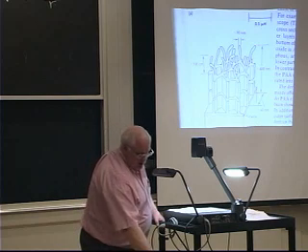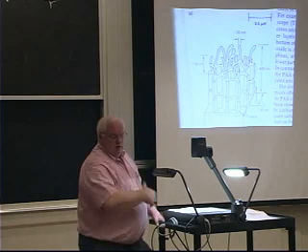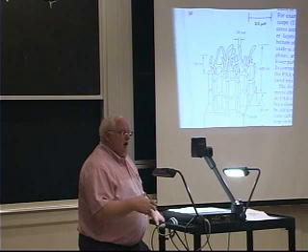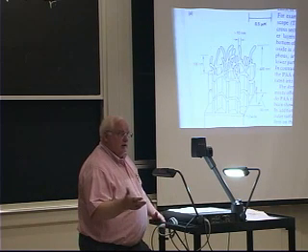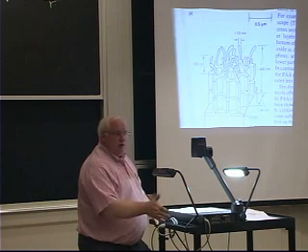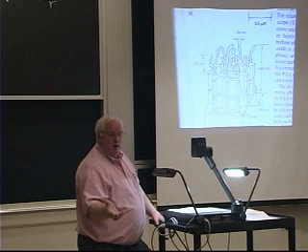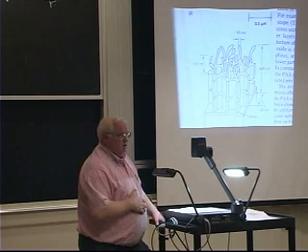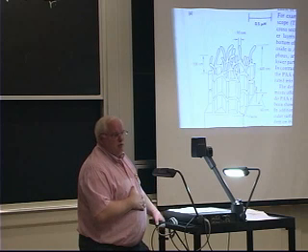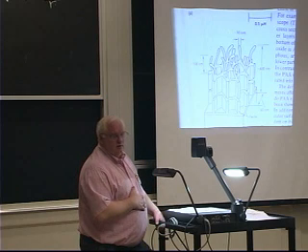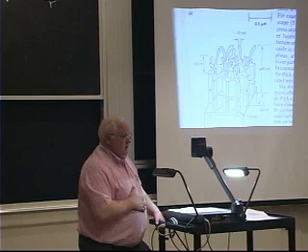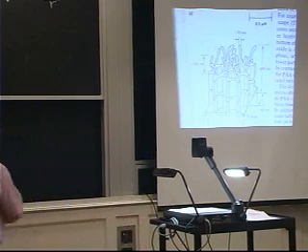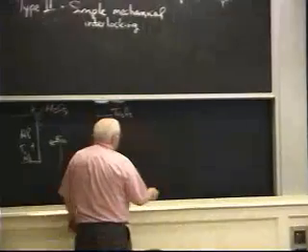My oldest son's Eagle Scout project was a bunch of railings, outdoor hand railings on a building. This is back in 1986 or 87. The building had been built in 85 and all the paint was coming off this galvanized steel two years later, just peeling off in great big sheets. They had done nothing to prep the surface of the zinc, the galvanized steel. Okay, they just painted it.